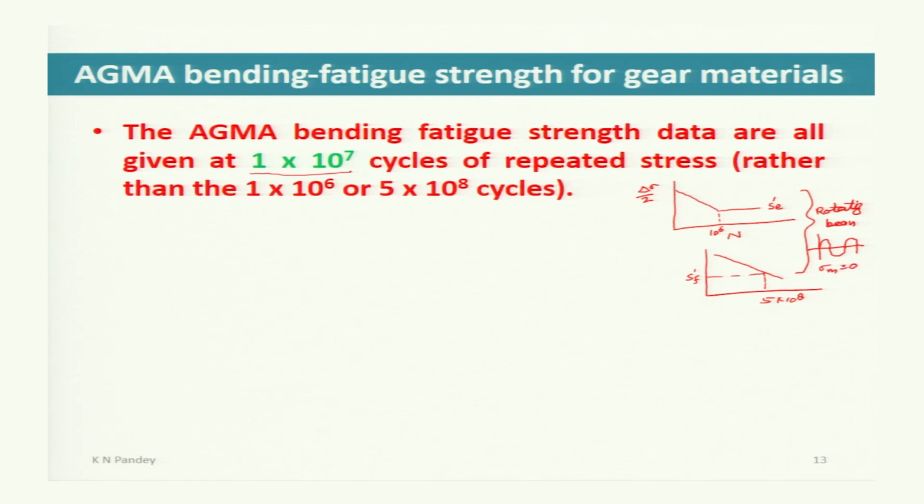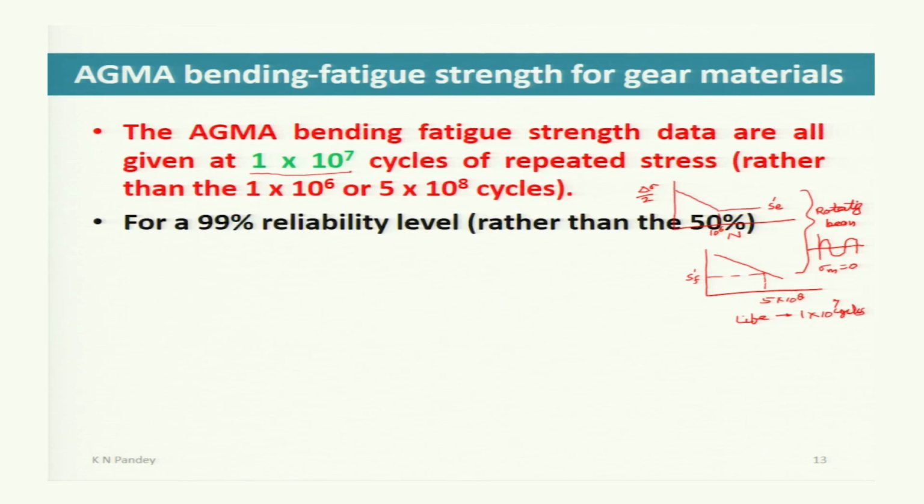Okay. So for most of the materials this type of data is there, but AGMA has provided the fatigue strength data for 1 into 10 to the power 7 number of cycles. So the data for fatigue strength are for life 1 into 10 to the power 7 cycles and reliability equal to 99%.